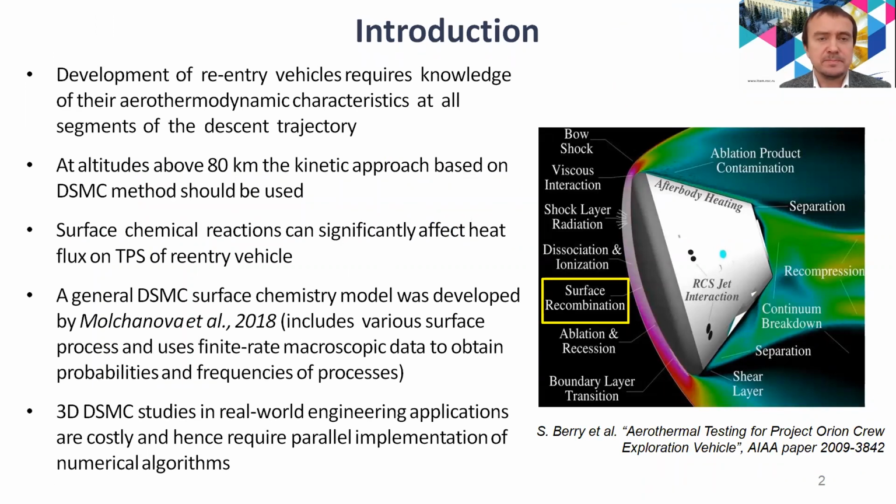The work is related to the problems of space vehicle high-altitude aerothermodynamics. Well, we know that at altitudes above approximately 80 kilometers, the continuum approach is not applicable, and this is why we use the kinetic approach, normally based on the direct simulation Monte Carlo, or DSMC, method.